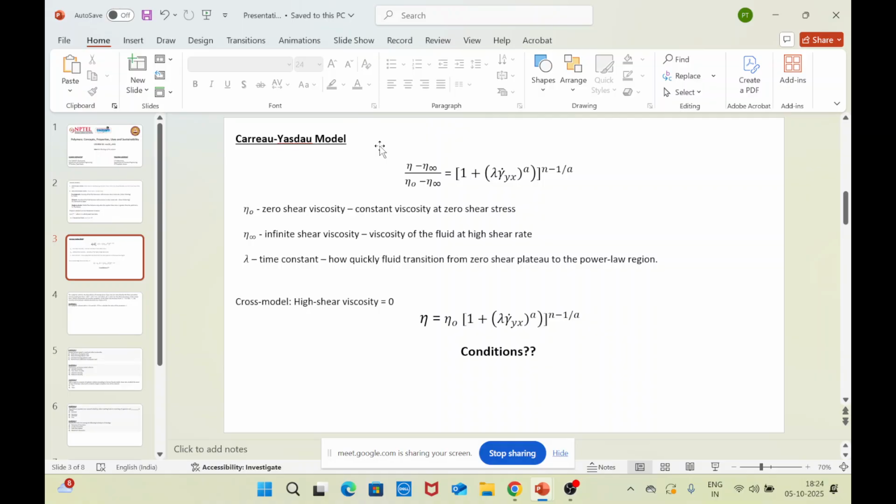In the case of linear and branched polymers, when you place them in solvents, two types of phenomena can happen. One is plasticization and the other is solubilization. Plasticization is a phenomenon where the solvent molecules in which you place your polymer act as a plasticizer, interact with the polymer, and increase the segmental flexibility of the polymer chain.